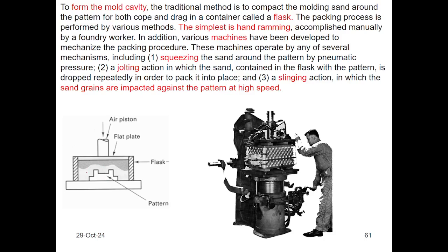To squeeze the sand particles to have the cavity indented in the geometry of the casting, a force is needed. A force is applied to push the sand particles toward the pattern. If the casting is a small size casting, then that force is applied using a flat plate or some tools by the technician, the foundry man.